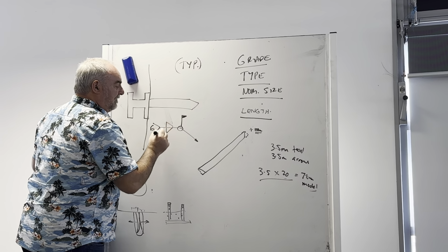But you've got to keep a little bit away from the weld, because the weld is in here like this, and there's your hole. You don't want the weld getting in the way of your nuts and bolts. You've got your bolt on top like that, and you need enough room to put a socket on top and screw it down. You can't have it hard against the weld.